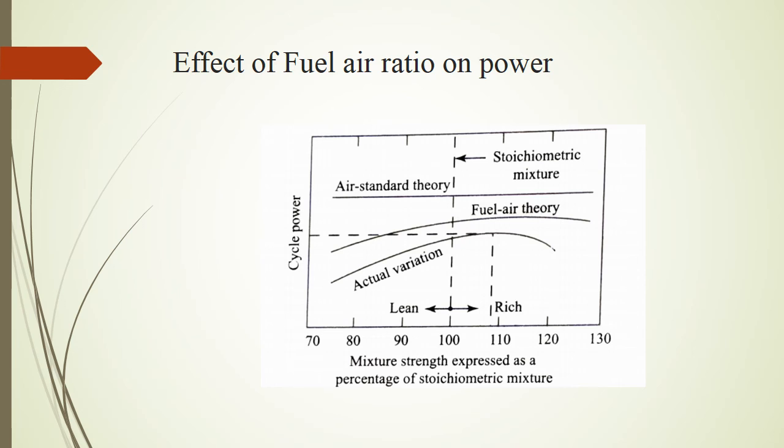It is basically because in addition to higher specific heats and chemical equilibrium losses, there is insufficient air, which will lead to the formation of CO and H2 during combustion, which represents a direct wastage of fuel. However, the fuel-air cycle analysis cannot exactly imitate the experimental curve due to various simplifications of the assumptions that are made.